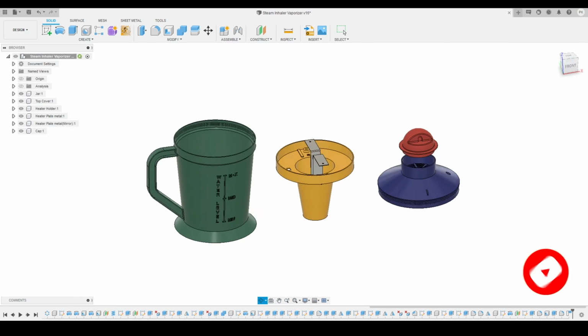What I can do is turn on the origin to see if it is aligned with the origin. If it is not, I can click on edit canvas over here, and I will move it a little bit to align it with the origin. So here you can see, and we'll press OK. Here you can see the work of this canvas is over for now.